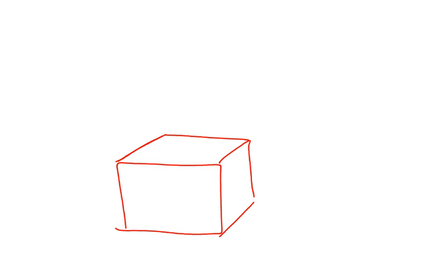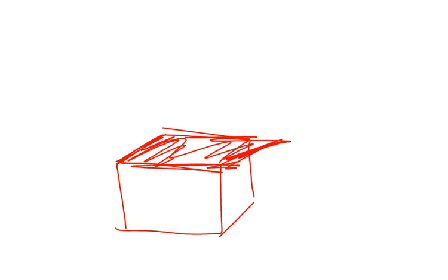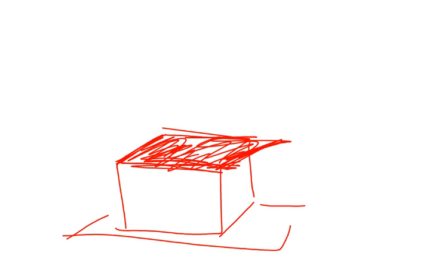I'm going to attach a very rigid plate to the top face. I clamp the bottom face. And then instead of pulling in tension or compression, I'm going to pull on this top plate horizontally. You can imagine what happens there. So I keep increasing that force. I take that force divided by the cross-sectional area. That's my shear stress.